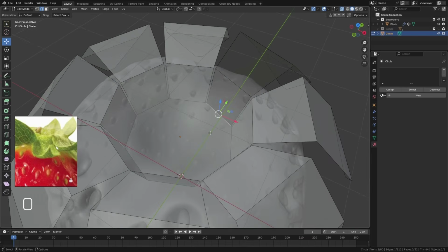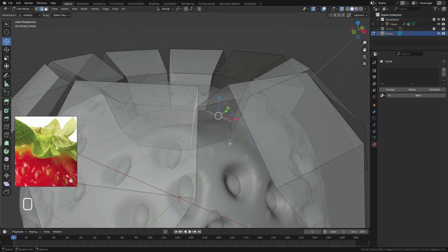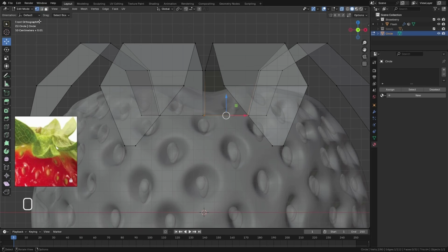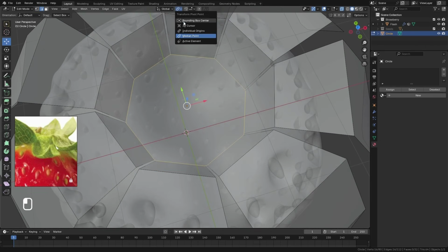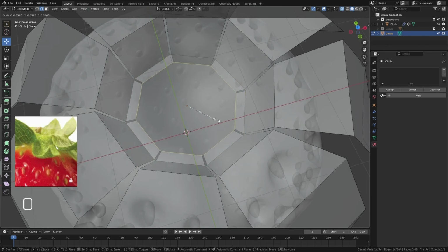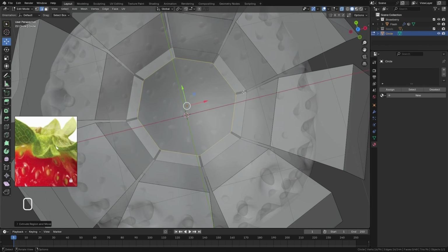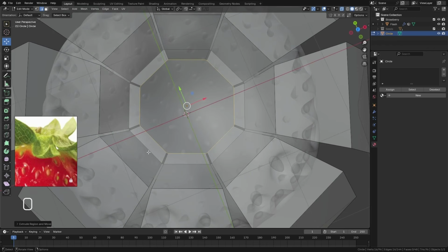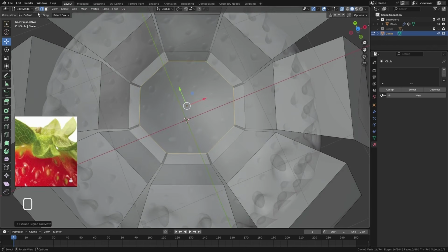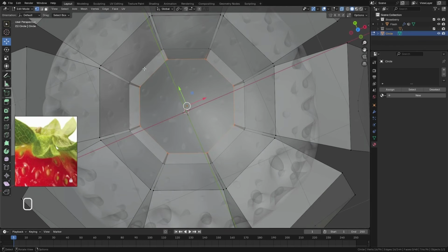So inside, let's select the vertices from front view right here, back to edge mode, and let's go E, S, one level. And I don't want this gap to continue to the center, so I'm going to stop it right here. Switch back to vertex, grab them all, and hit M, by distance. So merge by distance, and let's go one level, all merged together.